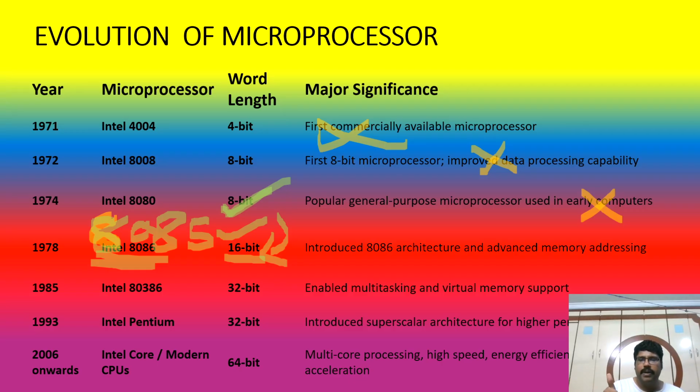Since it is an 8-bit microprocessor, it can process only 8 bits of data at a time. So automatically the speed will be reduced. Second, there is no proper instruction set. We cannot perform signed multiplication and division operations properly. If there is any negative number, if you perform multiplication and one of the two operands is negative, the answer may come as an abnormal result. Similar concept with division also, and there is no pipeline. These are the drawbacks of 8085.